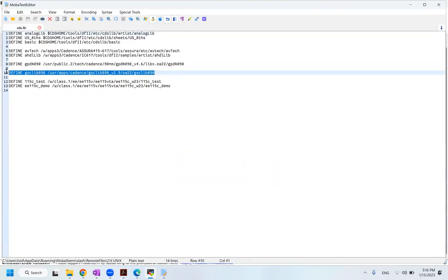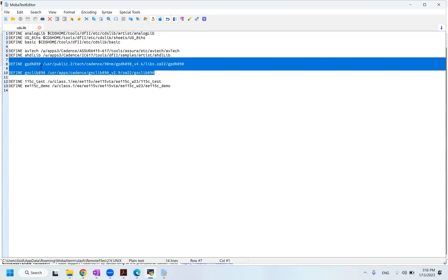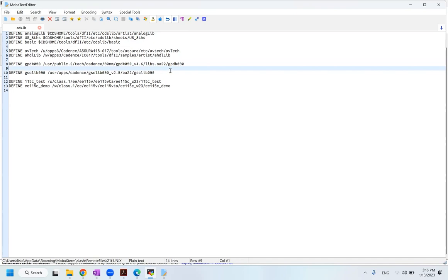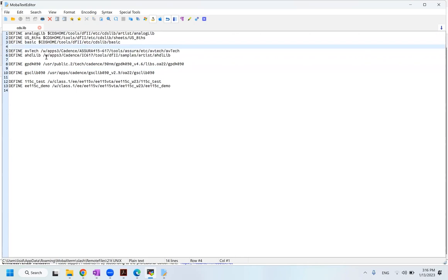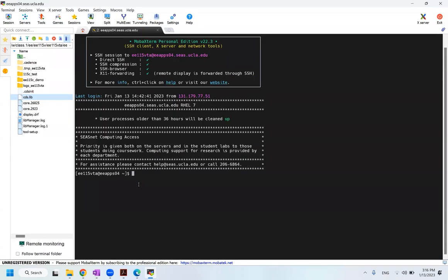So basically what we include is these two libraries, PDK 90 nanometer. It includes all the components under the 90 nanometer technology. Some basic cells include, like we use this analog lib, which has the power supply, the ground, all those kind of fundamental components.